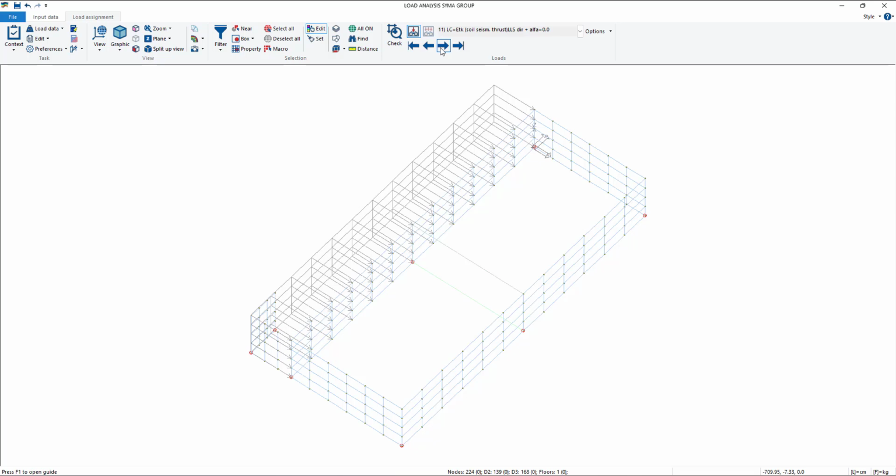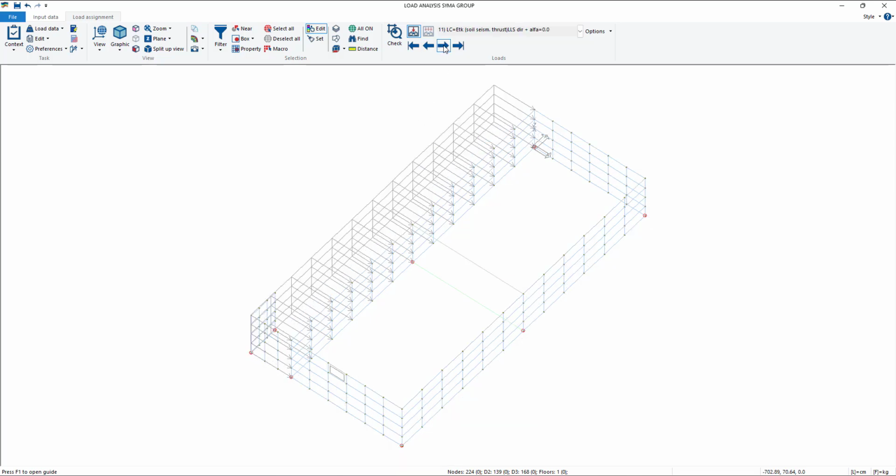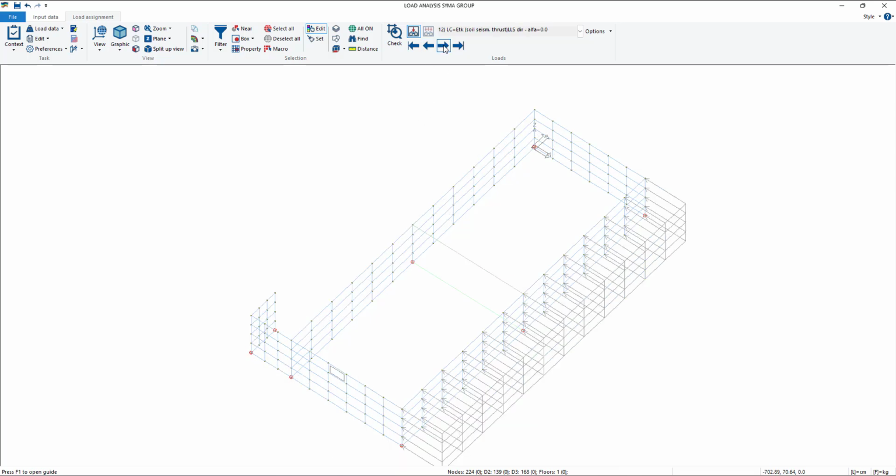These are our static loads, these are our dynamic loads. So pressure for the soil in different conditions, triangular ones for the static, and regular, uniform ones for the dynamic.